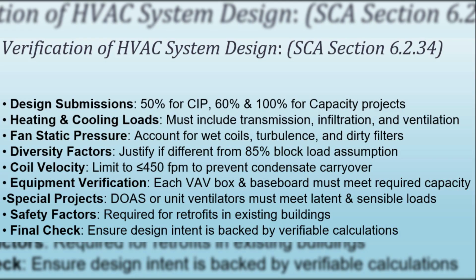Engineers must also justify diversity factors used in variable volume systems, especially if they differ from the typical 85% block load assumption. Finally, every VAV box and baseboard must be shown to meet its required capacity. In special cases, such as projects with tight floor-to-floor heights using dedicated outside air systems or unit ventilators, engineers must demonstrate that latent and sensible loads are fully met.